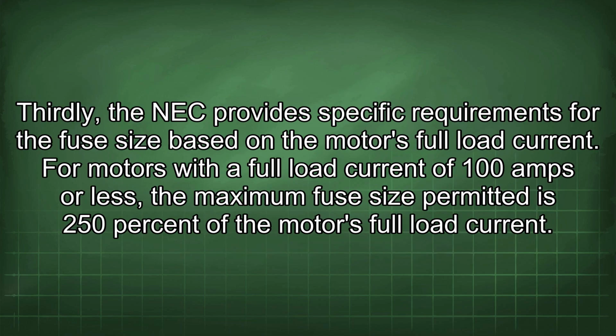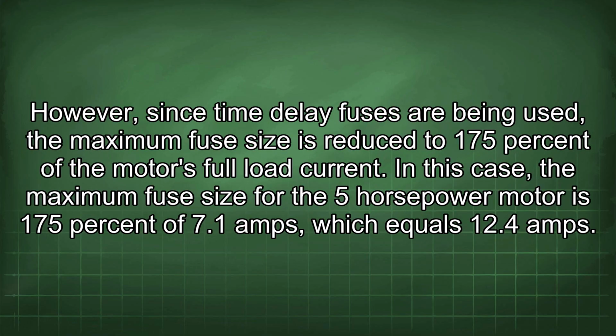Thirdly, the NEC provides specific requirements for the fuse size based on the motor's full load current. For motors with a full load current of 100 amps or less, the maximum fuse size permitted is 250% of the motor's full load current. However, since time delay fuses are being used, the maximum fuse size is reduced to 175% of the motor's full load current. In this case, the maximum fuse size for the 5 horsepower motor is 175% of 7.1 amps, which